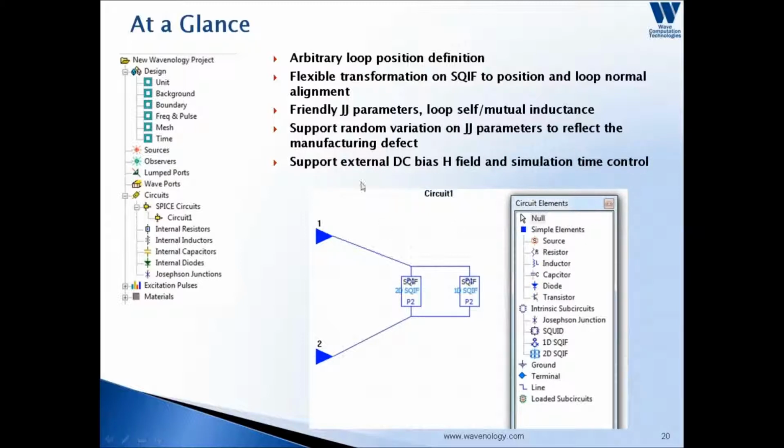We also support the external DC bias of the H field and the simulation time delay. Because this is a transient simulation, at the very beginning the DC bias has not yet stabilized the squid. So the user can ignore that part and only consider the stabilized portion.